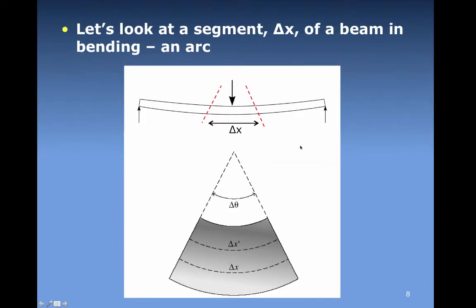If we take a general beam shown here, this is three-point bending, where there's a force applied at the center of the beam and it's supported or counterbalanced by two reaction forces at the edge of the beam. What we draw here is a general description of how an element within the middle of the beam deforms relative to an initially undeformed or straight segment. This is an expanded view shown here, and what we denote in here is this curvature that appears as a result of this applied loading.